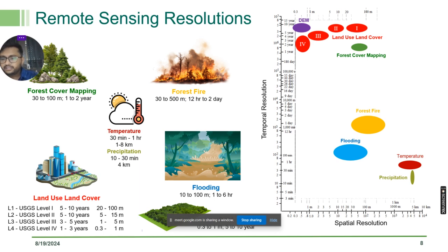And then we talk about meteorological variables such as temperature and precipitation. For measuring those phenomena, if the spatial resolution is coarser, then it is fine. But the temporal resolution should be very high. Like if I want to say whether flooding is going to happen in the next 2 or 3 hours or not, we need continuous data of temperature and precipitation, and based on that we will model floods using a hydrological model or any model which can predict flood, and then that will give warnings.